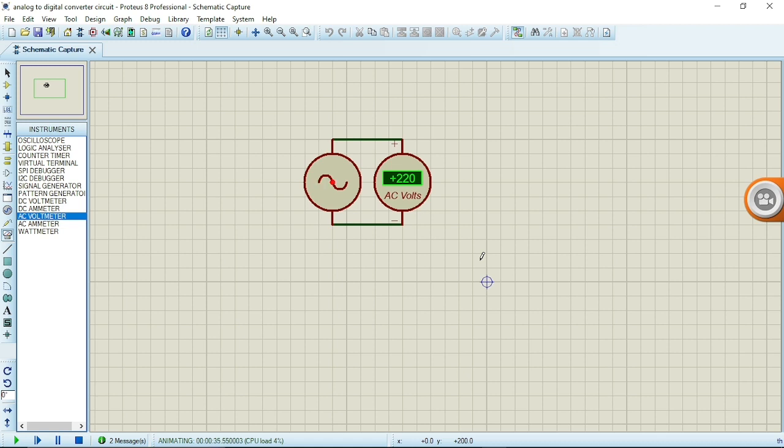The common way of doing this converter circuit is using a transformer. After the transformer, you use the rectifier, then you filter it with the capacitor, and boom, you have your converter circuit for anything you want to use it for. You stabilize it using a Zener diode or anything. But that way of doing it is very expensive, one, and second, it is very bulky. It is too bulky. But I am going to be showing the simplest way of doing this.